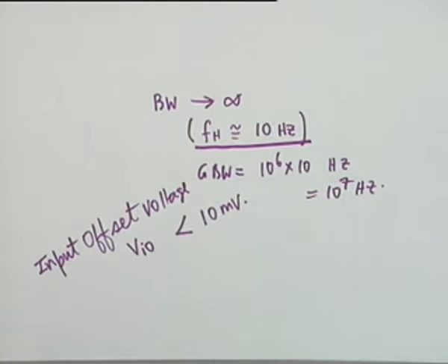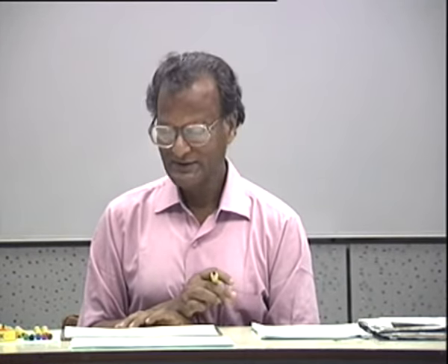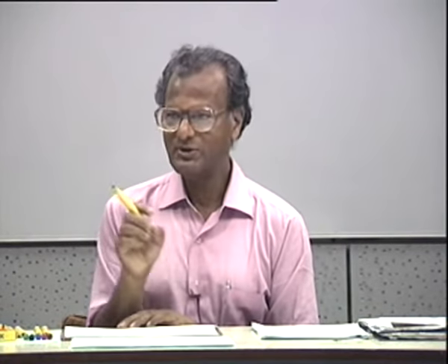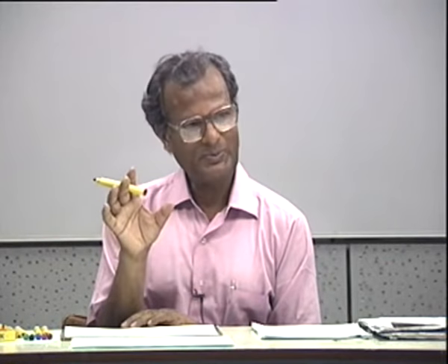The less the better. And you have seen that in some of the differential amplifiers a small emitter resistance Re is attached. For example, in the last Gilbert cell also, the voltage to current converter, we had an Re. This Re is usually used to balance the two transistors. Even if they are slightly mismatched, a small resistance used here, and this will be part of the fabrication, is adjusted like that. Even with that adjustment, you may have an op-amp in which there is an input voltage offset.